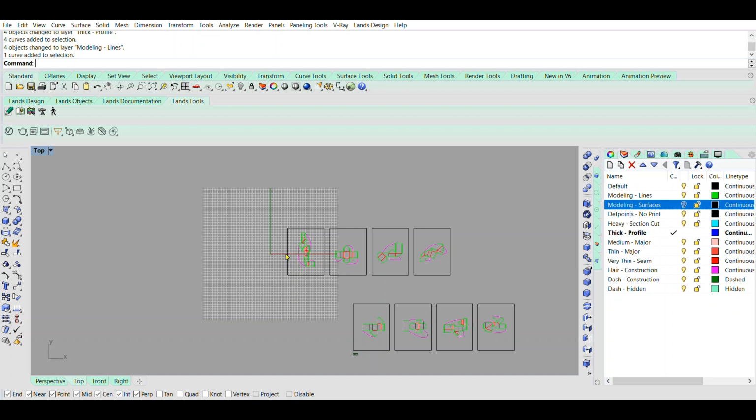And then also, when you open a DXF file in Illustrator, if some layers import and some others don't, it could be that you have a layer not set to print in that Rhino layer menu, such as depth points. Often these will not export until you change that setting, close out, and save in Rhino, then reopen and export again. If that still doesn't work, create a new layer and then move that line work over to that layer into an existing layer. So those are just some tips, and then let's go ahead and export.